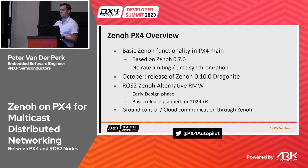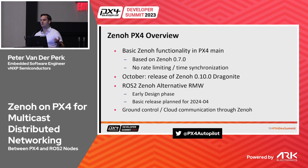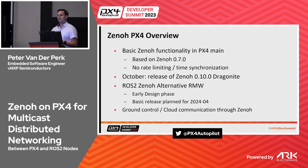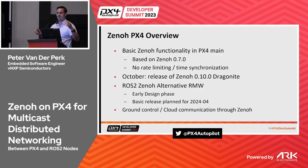But also what is very interesting is we go even smaller and just have a small sensor with an Ethernet connection, and we can just bring this into the ROS world or even into the PX4 world. And we don't have to play around with long I2C wires, the magnetics and other stuff, because if you look at Ethernet, and specifically automotive Ethernet we work with, it's quite fault tolerant. You don't have to shield your cables, so it would be very nice to be able to use that technology.